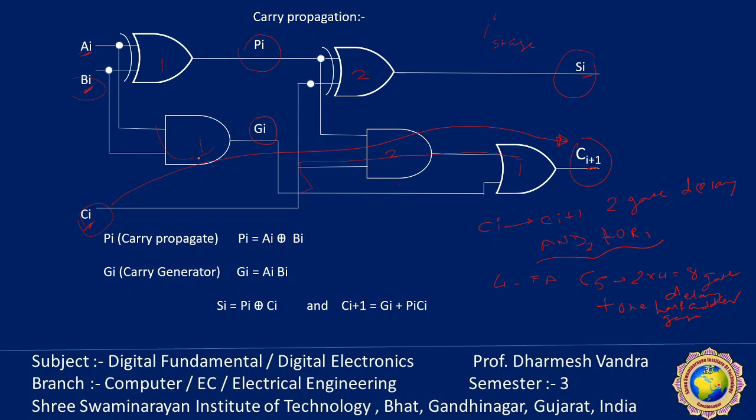An obvious solution for reducing the carry propagation delay time is to employ faster gates with reduced delay. But the physical circuit has a limit to its capability. Another solution is to increase the equipment complexity in such a way that the carry delay time is reduced. There are several techniques for reducing the carry propagation time in a parallel adder. The most widely used technique employs a look ahead carry generator.